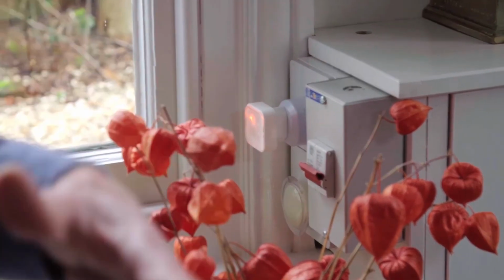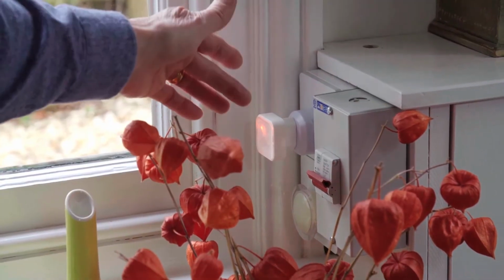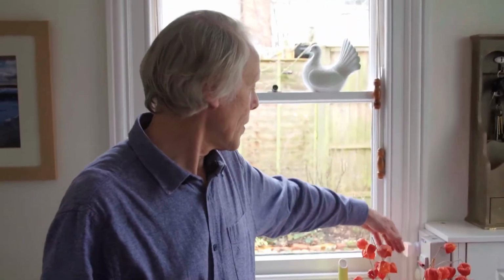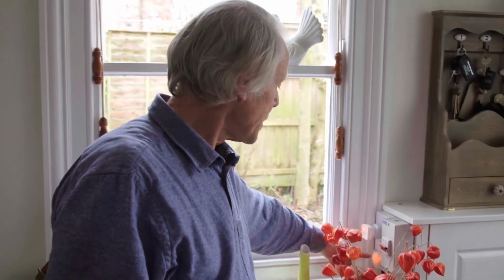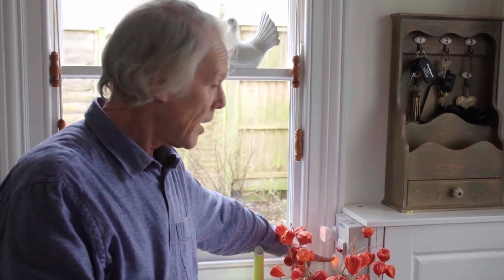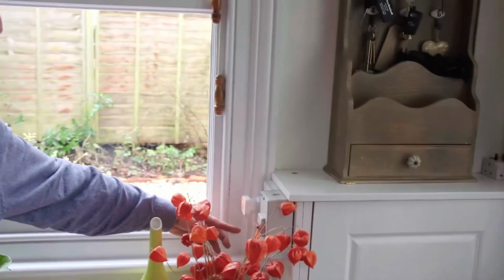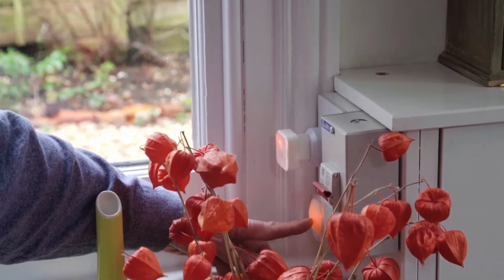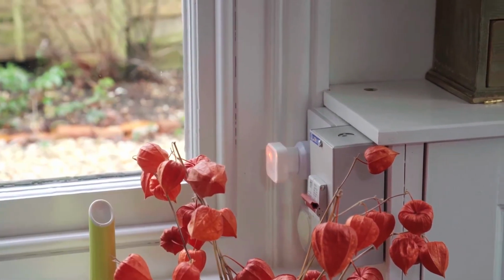Now the way the indicator light works is when the last light in the circuit is switched off, then the indicator light goes off. So I'm going to turn on a light for the upstairs circuit. So I turn it on, and as you can see, the bottom indicator light, which is for the upstairs circuit, has come on. So that tells us that the circuit is live. And then when we go to bed at night and we switch the last light in the circuit off, which I'll do now, if you watch this indicator light, it takes a few seconds, but then it'll go off. There we are. And then that tells us that the power to that circuit has been cut.